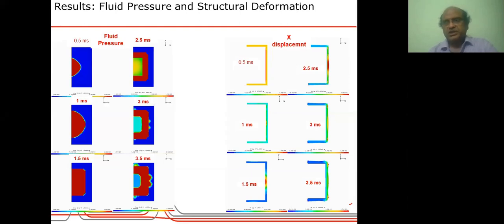When we couple these, we can use two different time steps: a smaller time step for the fluid flow solver and a larger time step for the structural solver. So a segregated solver allows more freedom in adjusting this kind of solution parameter, which will reduce the total computational time.